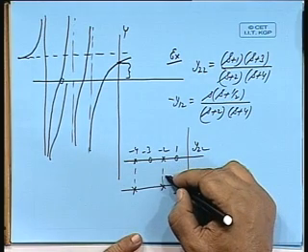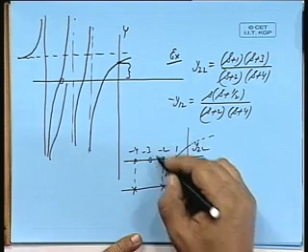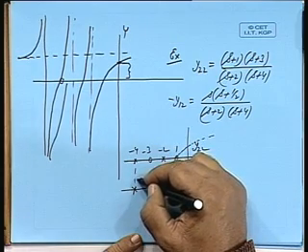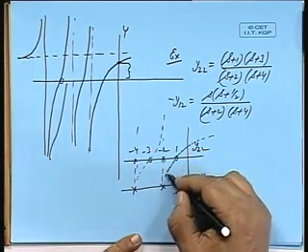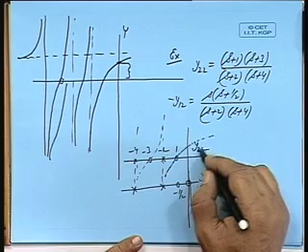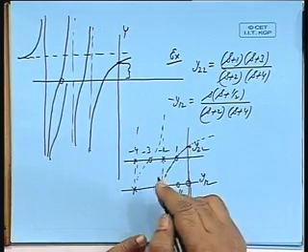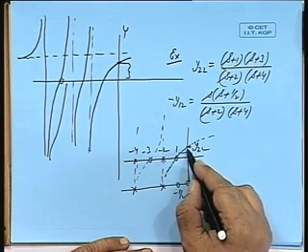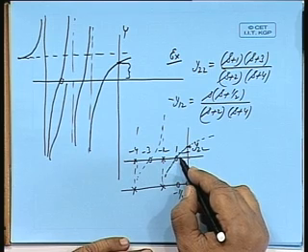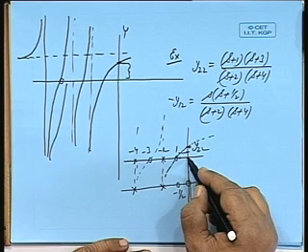In the original one, this will be the nature of pole 0, this is the admittance diagram for y22. So, it is part of this that I am going to remove, maybe this much I remove. If I remove this much, then this will be the new 0 location, is that all right? If I remove it totally, then this 0 will come here, is that so?